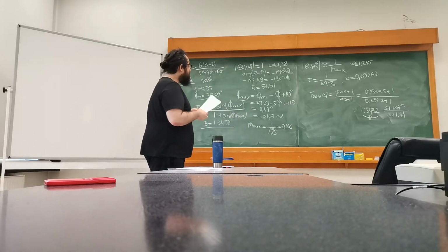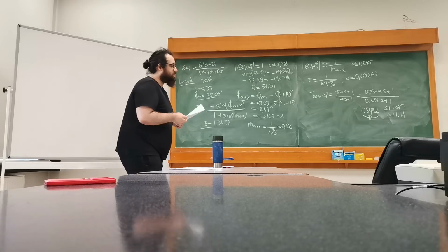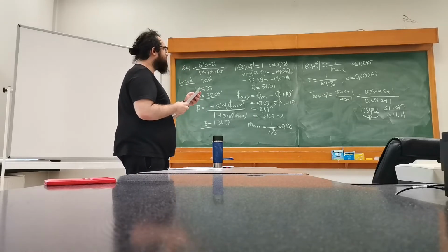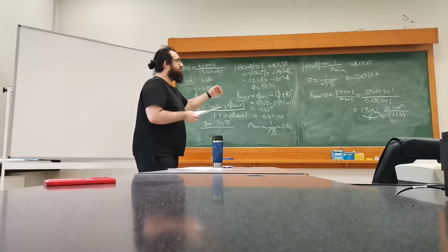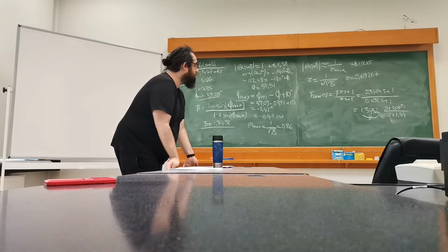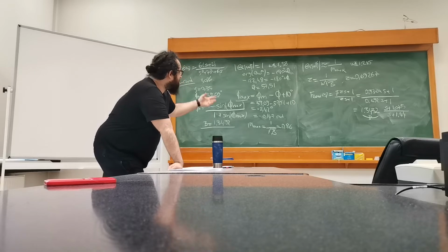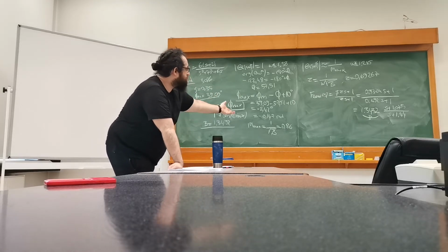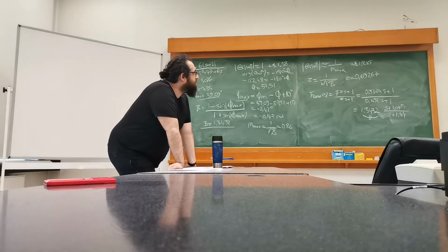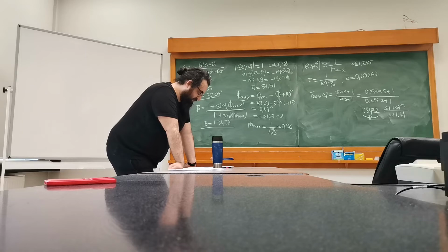So it's not really that interesting to design a lead controller if you are trying to teach it in a classroom, because it's too algorithmic, even more algorithmic than the lag controller. You have to find the phi max value, transition into beta, use the beta value to come up with a gain value, and then look up the inverse of the gain value. You have tau, and then we're basically done.